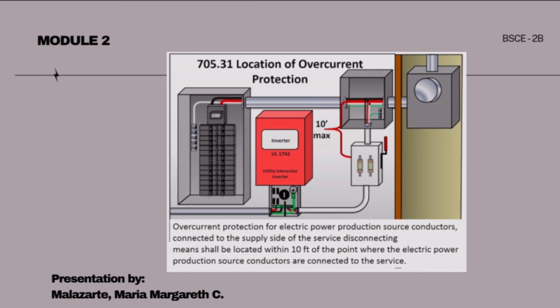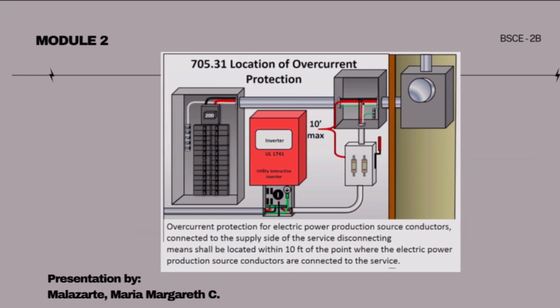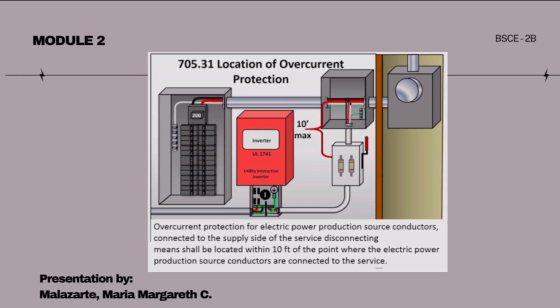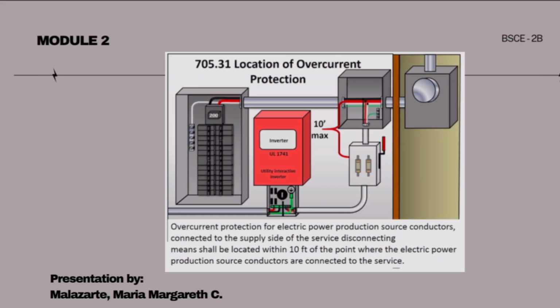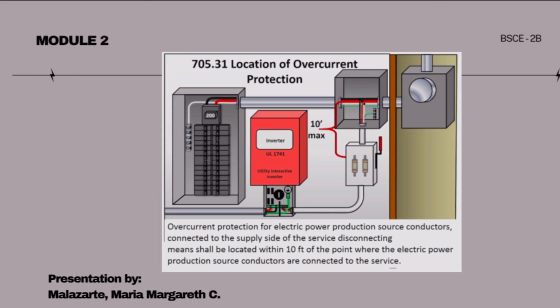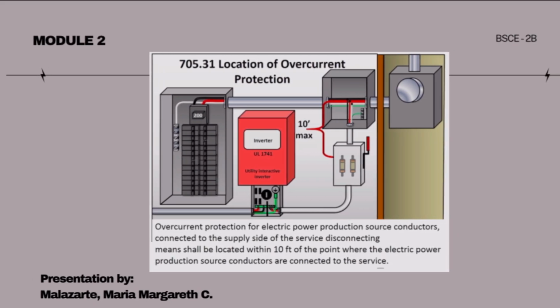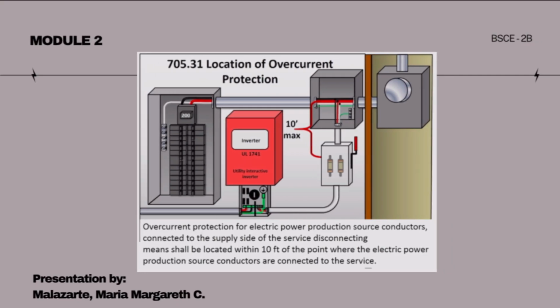To continue, let's talk about the overcurrent protection devices, or the OCPD. They safeguard the building service or an individual circuit from excessive current flows. It protects the circuit components from severe overheating when current flowing through the circuit reaches an amperage that will cause an excessive or dangerous temperature rise in conductors. Fuses and circuit breakers serve as automatic overcurrent protection devices. They are designed to open a circuit if the amount of current in amps that flows through the circuit exceeds the OCP device rating.